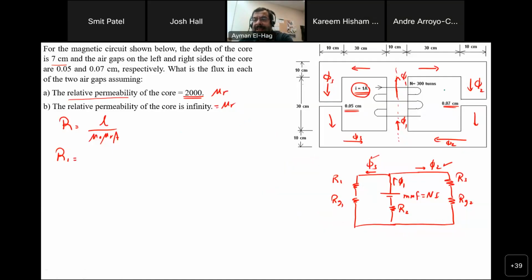Okay, so L starts from the point where the flux is starting. So this is L, going all the way until it reaches its end. Now, at this point, you will start to have a different flux. So phi 3 starts from this point, which I will call point A, and terminates at point B. And then we have different fluxes. So this is my L. When we want to find L, we start from the middle of the magnetic material. We don't take the outer or the inner path, but the middle, the average between the outer and the inner.